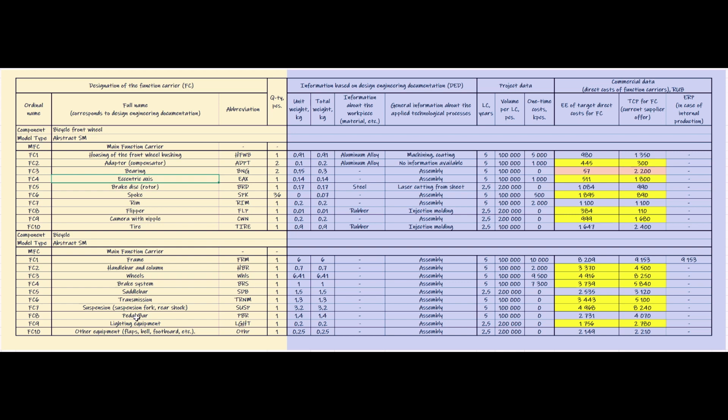The discrepancy between the number of function carriers and the number of functions may be more significant, as can be seen from the example of the bolt and the sleeve housing, for which our ratio was 7:16 and 14:33 respectively. That is, for a full and close to complete functional model, the number of function carriers is about 2.5 times less than the number of functions.